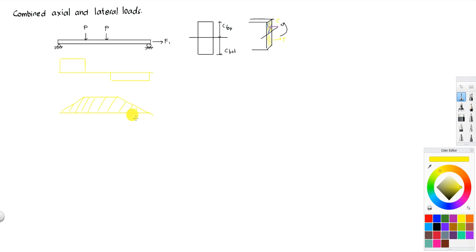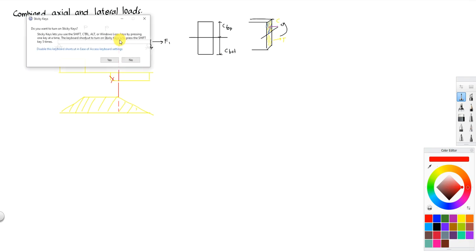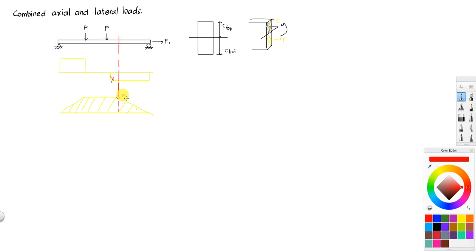For example, at this point. Because I have a moment there, I have P over A. And then again, this tells us where the compression is. To easily know where it is, look at the moment diagram of the beam; the compressive force is where the moment is. So in short, the moment is at the top, so the compression is at the top.